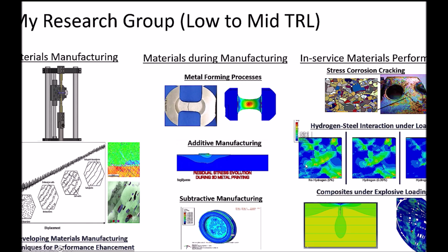In this case, the main mechanism was that the hydrogen diffuses in the lattice spaces, then diffuses around and goes to the interstitial sites, and that causes the change in the material properties, and we accounted for that in our model.